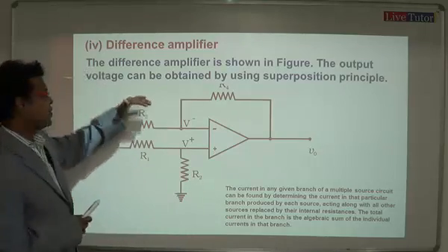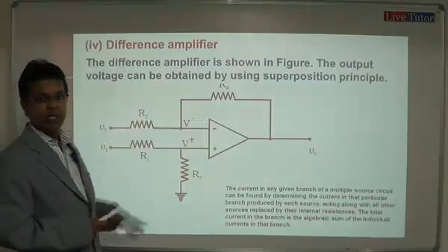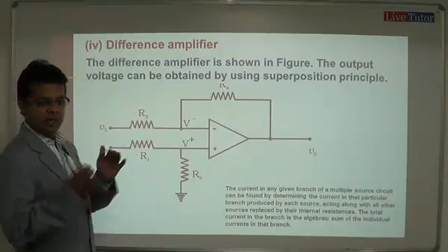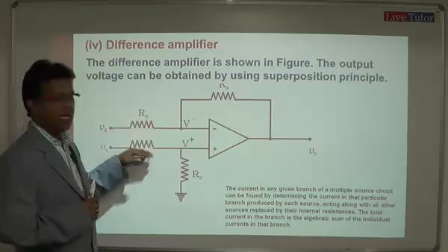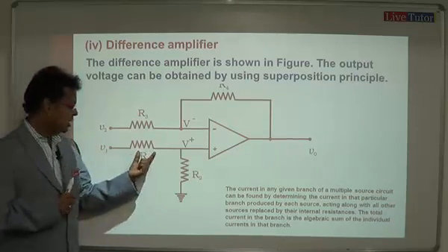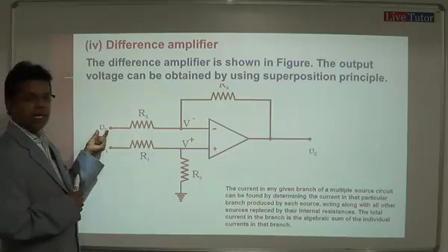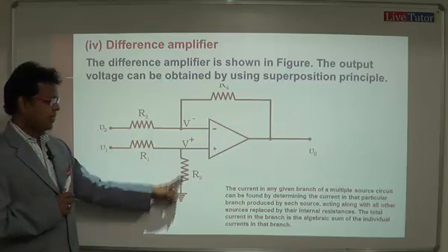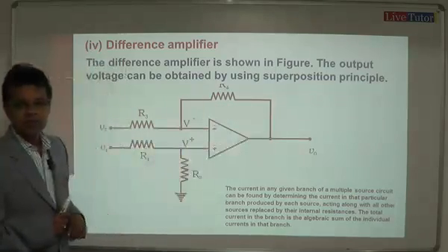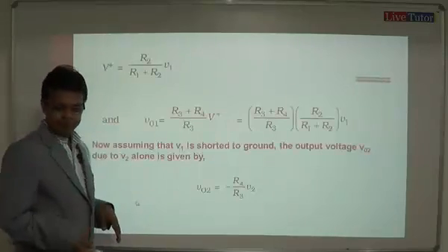So as usual you will write that the difference amplifier using the operational amplifier is shown below அப்படின்னு எழுதி டயகிராம் போட்டுருங்க. And in this we are going to use both the terminals. ஏன்னா டிஃபரன்ஸ் கண்டுபிடிக்கிறதுனால இன்வெர்ட்டிங் நான் இன்வெர்ட்டிங் ரெண்டுத்தையுமே இன்புட் கொடுக்கிறோம். நான் இன்வெர்ட்டிங்ல V1 that is first voltage, இன்வெர்ட்டிங்ல செகண்ட் voltage, and this is grounded. And as usual இங்க வந்து fourth ரெசிஸ்டர் இருக்கு, feedback resistor. Okay, so this is the diagram for the last difference amplifier.